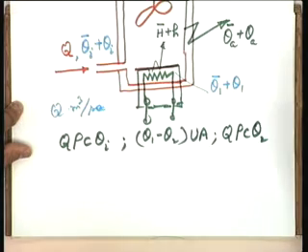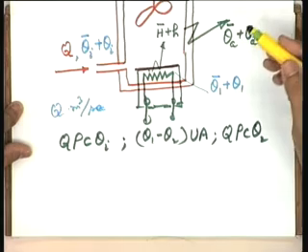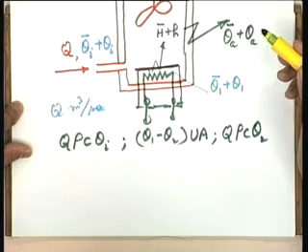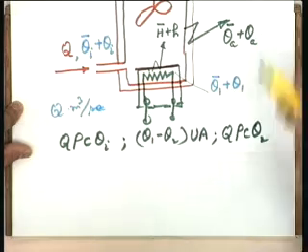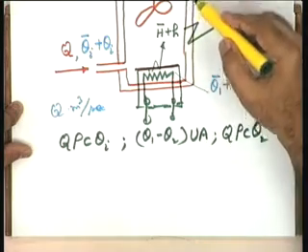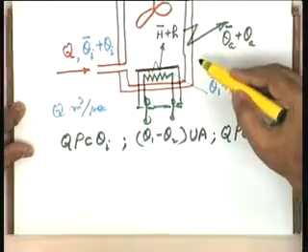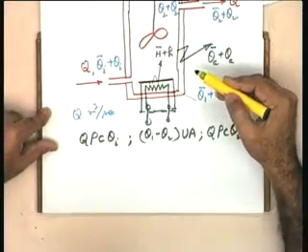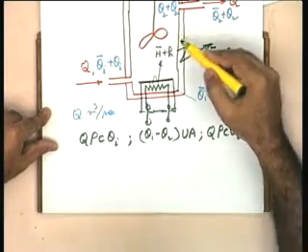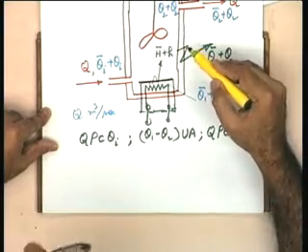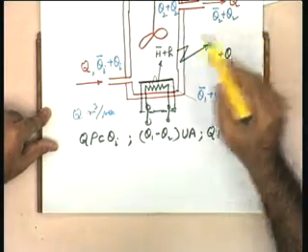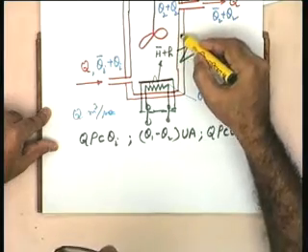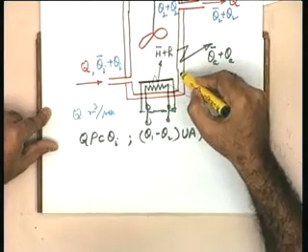And lastly, let us see what is the heat lost to the environment. Here you help me, what is the heat lost to the environment? Well, there could be some storage of heat in the tank walls. Certain approximations are to be made, and let me make an approximation that the heat storage of the tank walls is negligible, and I assume the tank walls to be at the temperature theta 2 itself.